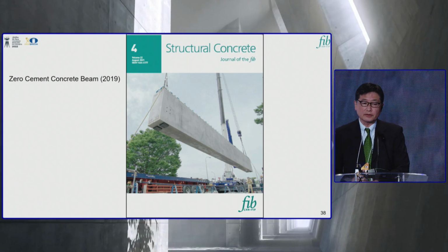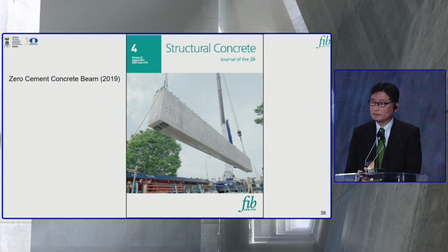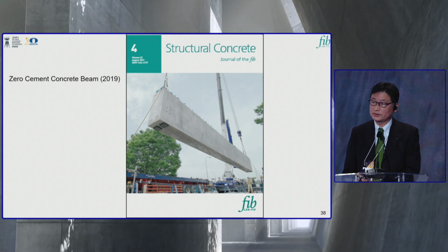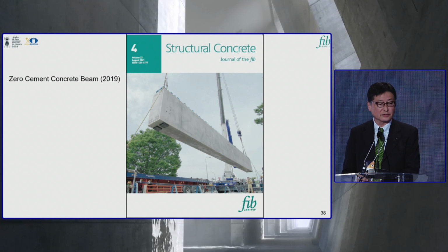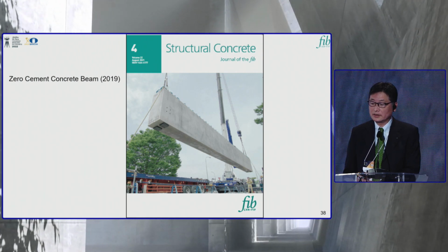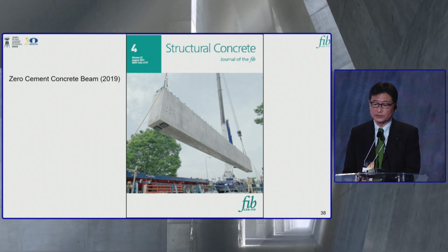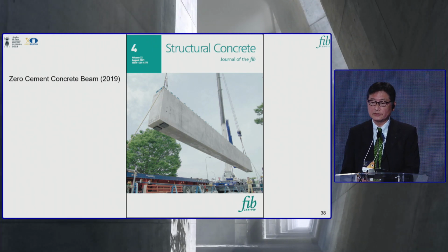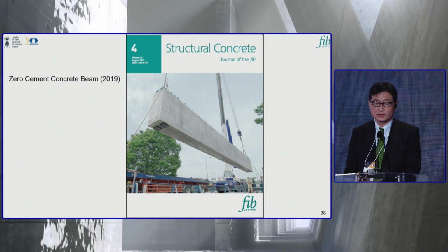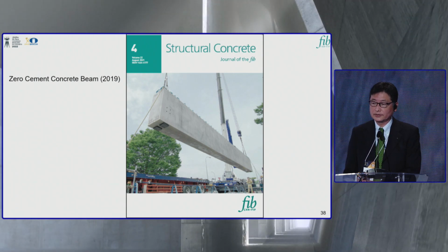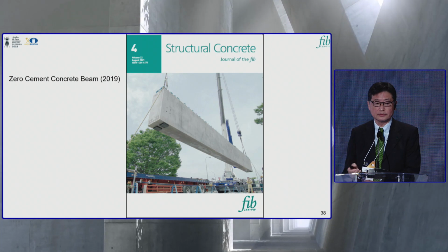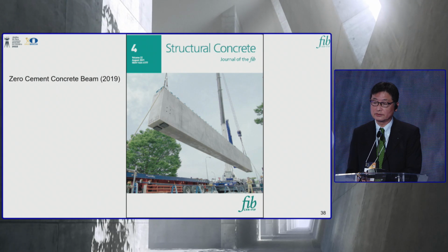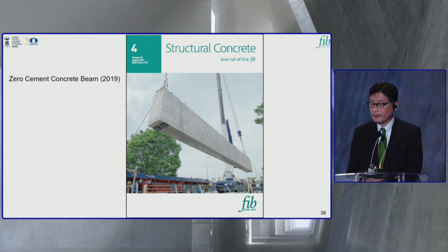This expansive additive is a very special material, but usually we use it in normal concrete, and this material is calcium based. Now we are doing joint research with Sheffield University, but in Europe it is not impossible to procure this expansive additive. So we are looking for another alkali activator to realize this zero cement concrete.